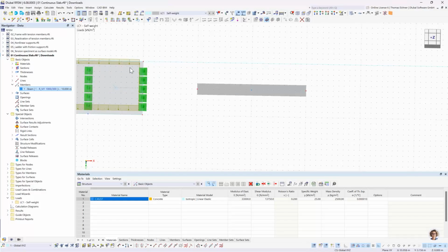For this plate, we did only fix the Z direction. Now for the member, if we think about it, if we only fixed the Z direction of this member, that seems okay in the first step. But the problem is it could rotate around its own axis.